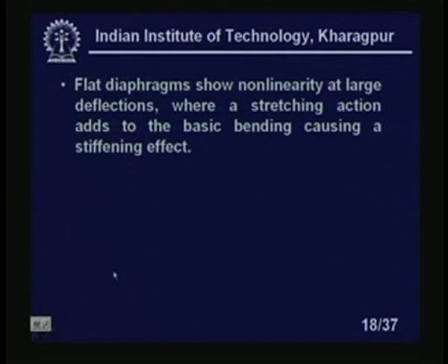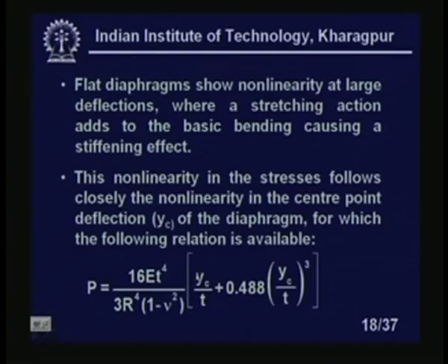Now, a flat diaphragm shows nonlinearity at large deflections, whereas stretching action adds to the basic bending, causing a stiffening effect. So, the deflection of the central point has to be kept minimum, otherwise there will be distortions. This nonlinearity in these stresses follows closely the nonlinearity in the center point deflection YC of the diaphragm, for which the following relation is available.